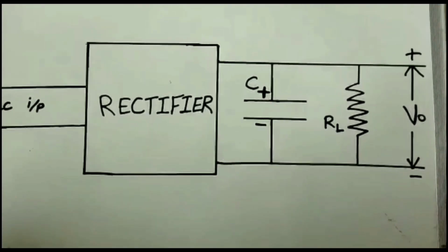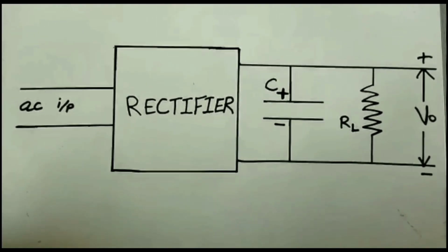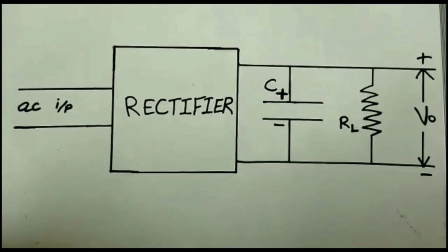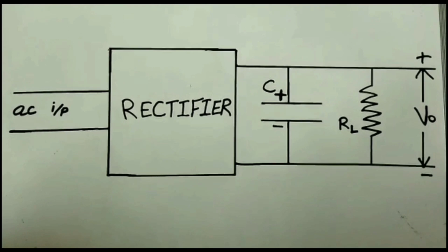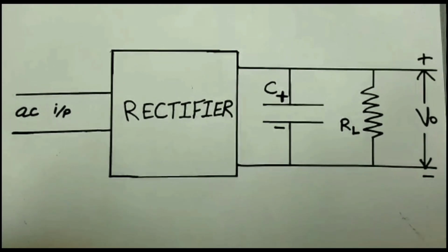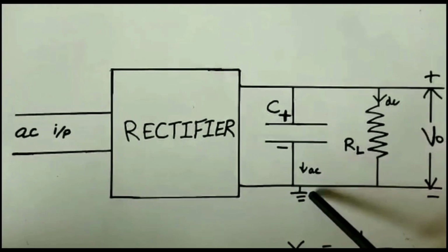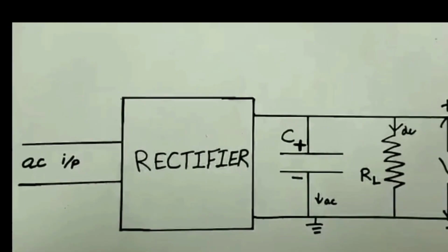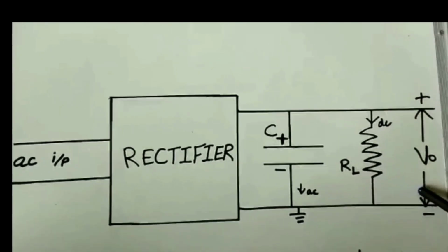Capacitor C acts as an open circuit for DC, that is, it does not allow DC, and provides a low reactance path for the AC components of the current. Now, the AC gets bypassed to the ground through C. The DC passes only through the load and produces DC output voltage.